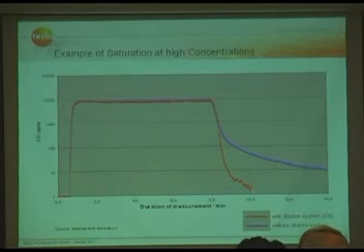And this is important if you do a long-term test over a few hours or days. You can program a measurement, like I need to measure for half an hour and I would like to rinse for 10 minutes, and this is for the next 2 days. And if you're not careful, or if high concentrations occur during the measurement, it is very typical that the sensor starts drifting.